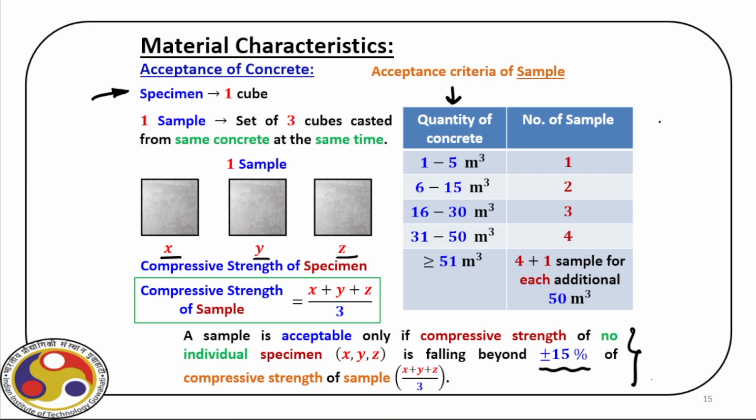Now, what is the reason for that? Because if we have, say, a concrete mold of 150 by 150 by 150, although the concrete comes from the same batch, we need to carefully prepare this concrete cube, and for that we need to fill it in parts, and every part we have to tamp with a tamping rod, and then finally fill the complete cube.